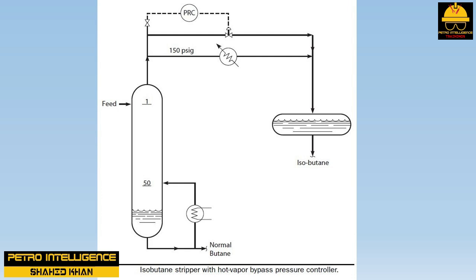As shown in this picture, this column has no reflux. This is a typical design for strippers. When feed is introduced on the top tray, there is no need for reflux. In order to improve tray efficiency, it will be necessary to increase the vapor velocity through the trays, to increase the pressure drop to at least 4 or 5 inches of liquid per tray.